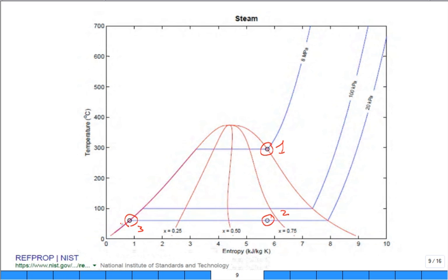And I'm going to pause. Don't shout it out. I'm going to walk around and I want you to show me on your rendition of a temperature entropy diagram, where is state 4? Where is state 4? It's going to be the output of the pump. We knew where state 4 was before, right? But we changed where state 3 is, and I'm showing you where the new state 3 is right there. Isn't state 3 saturated liquid at the low pressure? Now where is state 4?